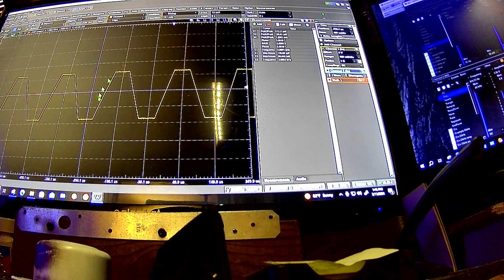And I'm saying in a normal situation though, where you have a fixed voltage output on a DAC, the vertical resolution actually does limit you at some point, especially if you have a high resolution signal. Eventually you run out of resolution. You've got to start cutting corners somewhere, so things start to get choppy. But at any rate, that's just another little thing to look at.